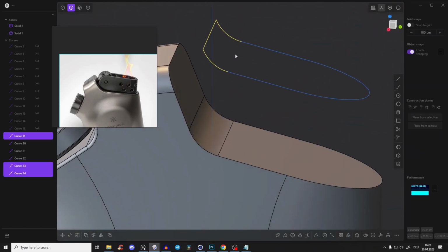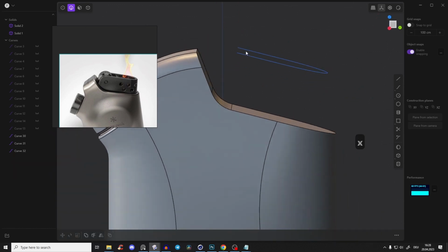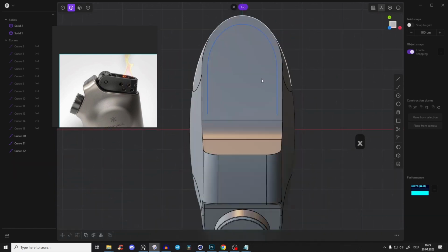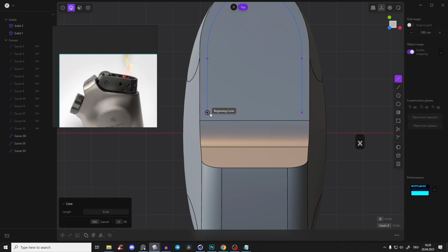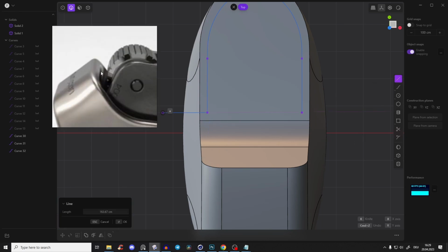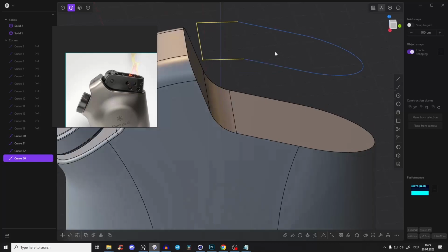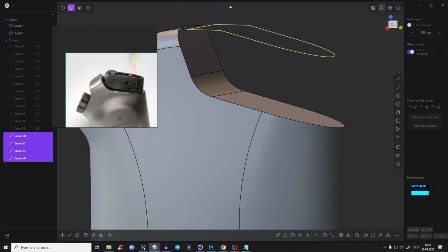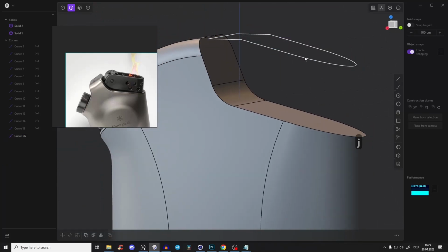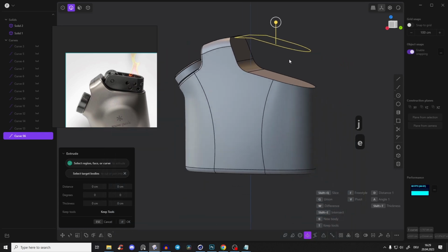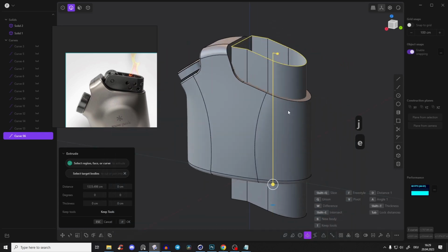And we can delete those pieces here, and we can go to the top view and just create a new line here, beginning to curve, and just adjust it so we can create this edge. So somewhere here, go to this point, press Shift, so you have a construction line, so you will meet it here exactly. And fine. So now again, select all of those curves, press J, so it's one curve. And now just press E to extrude it and just drag it downwards.